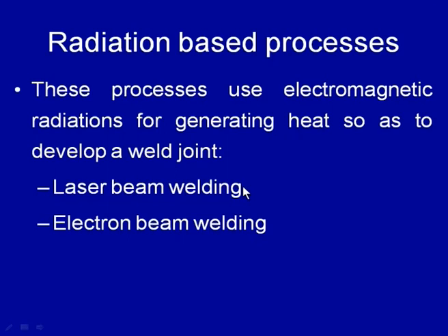Especially when using a laser beam of very small diameter, say 100 micron or 200 micron, the edge preparation becomes very critical. Otherwise, if there is any lack of straightness or roughness in the edges of the plates to be joined, then the beam will pass through the gap and the melting will not occur.